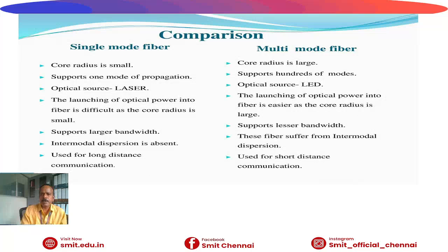In the multi-mode optical fiber, the core radius is large. More than hundreds of modes can be propagated. Generally, it uses an LED as a source. It supports very little bandwidth. Intermodal dispersion will always be there. It is particularly meant for short distance communication.